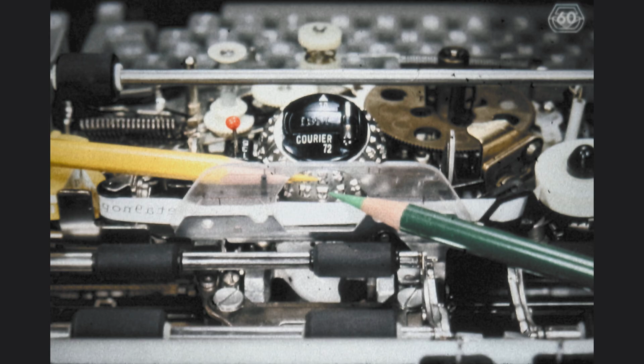After we loosen the indicated nut, raising the position of the detent actuating lever brings us closer to the pivot point of the tilt detent, and as a result, we get more output motion for the tilt and rotate detents. When we lower the screw which holds the detent actuating lever, we move the actuating lever away from the pivot point of the tilt detent, and the total motion transmitted to the tilt and rotate detents is decreased.